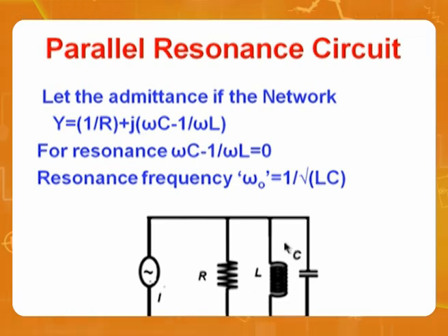So please remember, this is for all the three in parallel. Otherwise, if it is here, it becomes slightly changed. Now, which one is practical? This is theoretical, but if you put this resistor inside the inductor, that becomes the practical circuit. That's called the parallel resonant practical circuit.